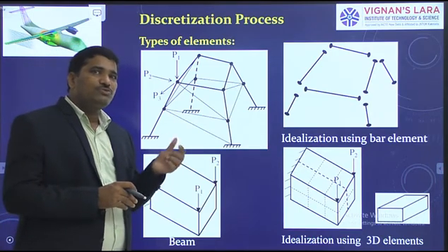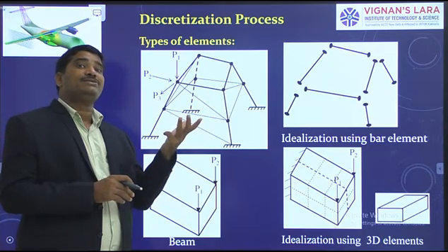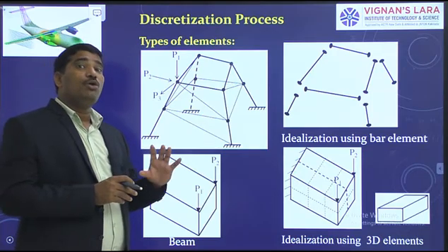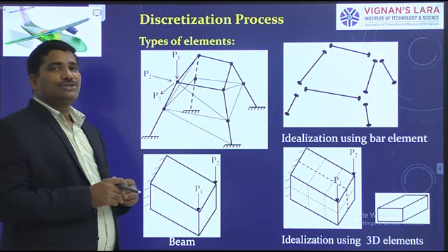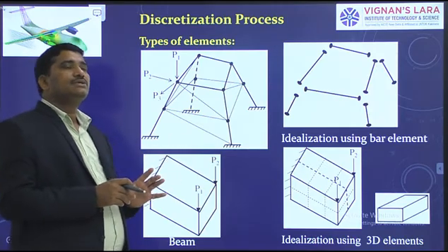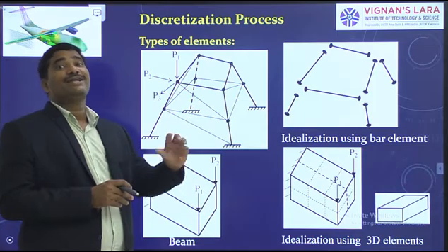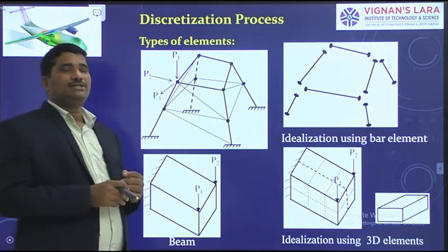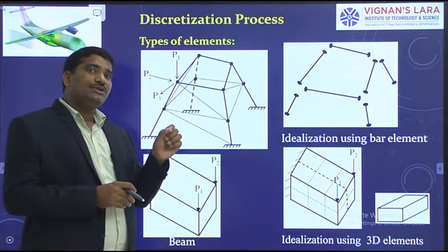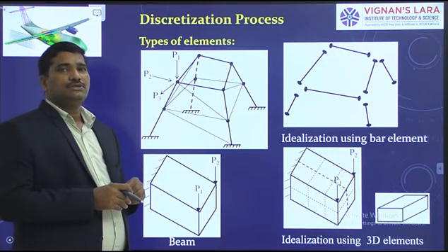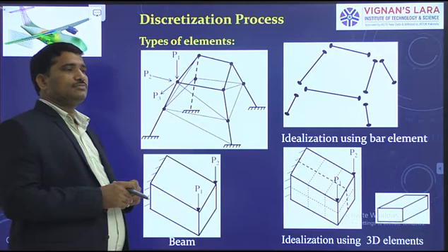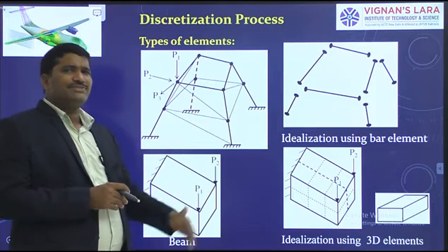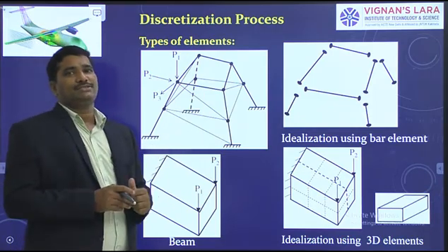when you choose elements with smaller sizes, the number of elements will increase, then the computation time increases. Then the computers require more storage. So this is the reason why engineers have to work with fewer elements for better solutions. Thereby the computation time is also decreasing. And third, where you choose the node, that is also a question. So selection of the node. Next, how you number the nodes, another question. So all these we discuss in the discretization process.